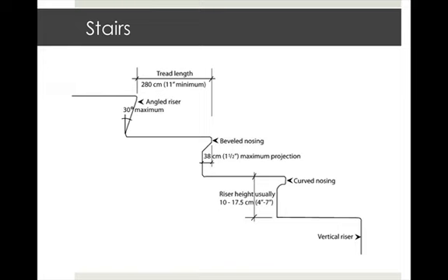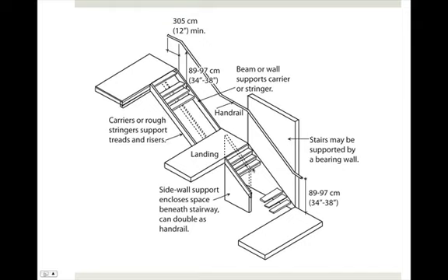A flight of stairs may not rise more than 12 feet without providing a landing, and the landing must be as deep as the stair is wide. A landing must also be provided at the bottom of the stairway and at the top of the stairway.